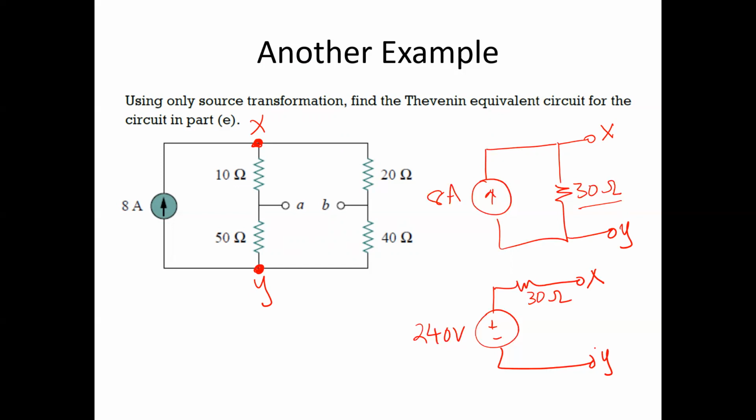And so the key thing that I wanted you to realize was simply that the nodes that you were drawing out from the Thevenin by doing combination and then source transformation are not the same as AB, okay? In order to find AB, you can't actually source transform from A and B because nothing actually combines.